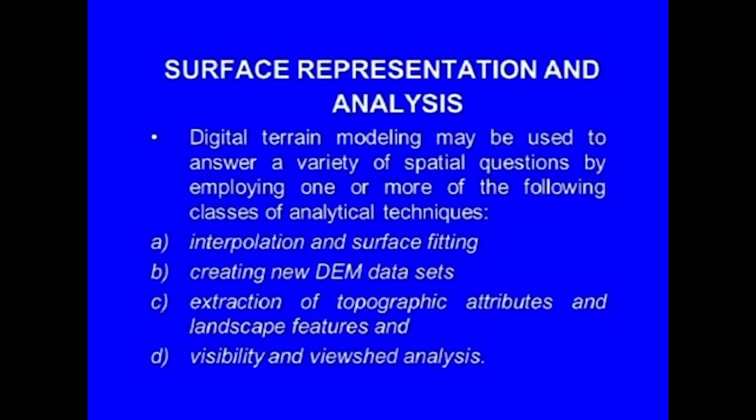Digital modeling may be used to answer a variety of spatial questions by employing one or more of the following classes of analytical techniques: interpolation and surface fitting, creating new DEM data sets, extraction of topographic attributes and landscape features, and visibility and viewshed analysis. So, let us look at interpolation and surface fitting.